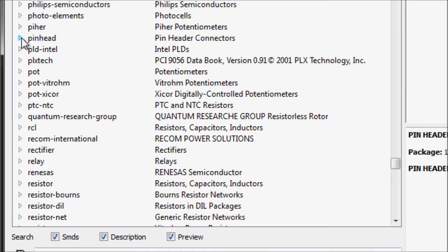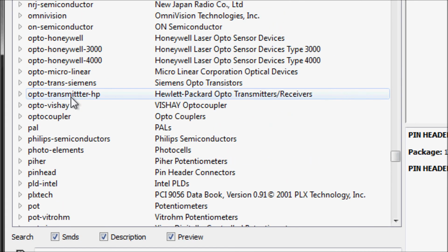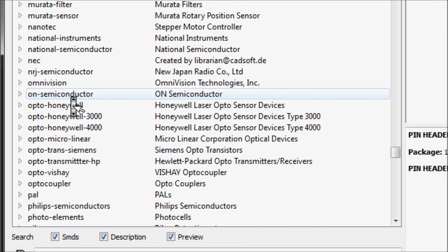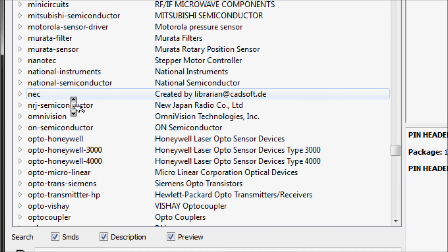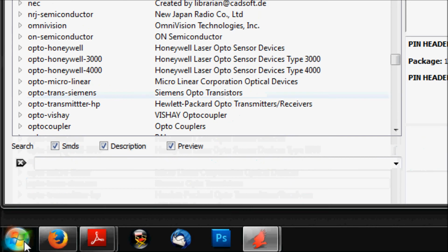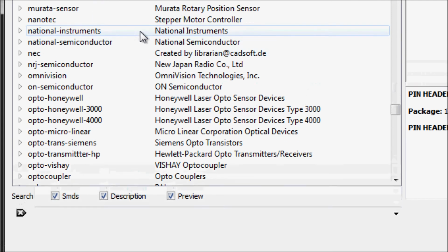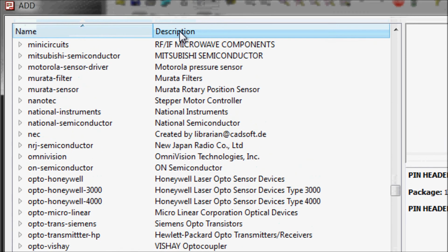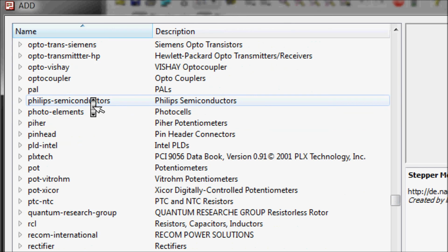Now, most surface mount devices, be it resistors or capacitors, are encased in 0805 packages. This indicates a length of 0.08 inches, not mm, and a width of 0.05 inches. The 0805 package is pretty much the standard for surface mount technology, so you will most likely be using this package unless your data sheet specifies some other dimensions. First, let's look at the 0805 package.